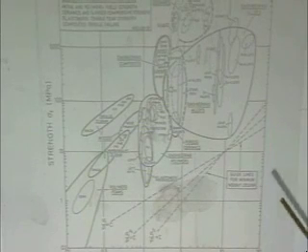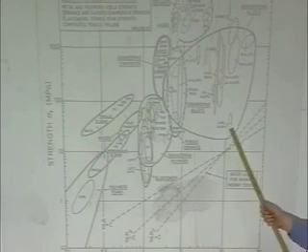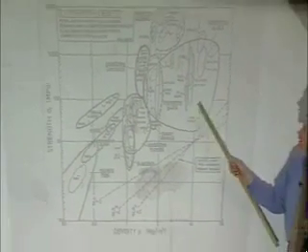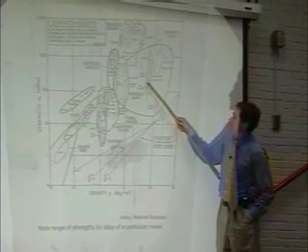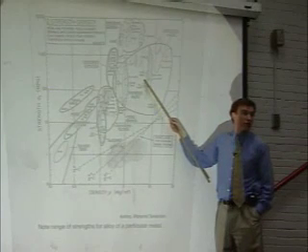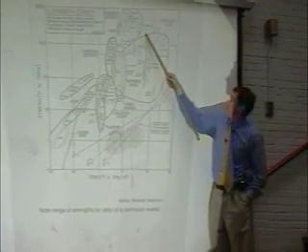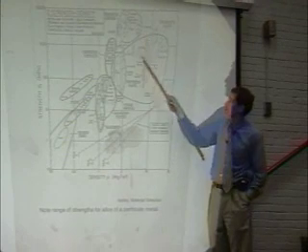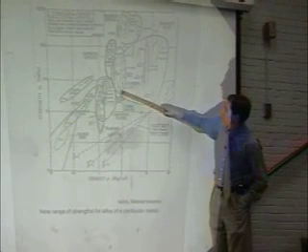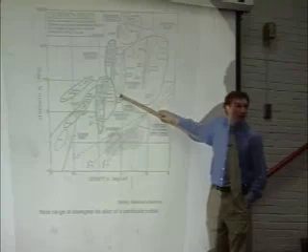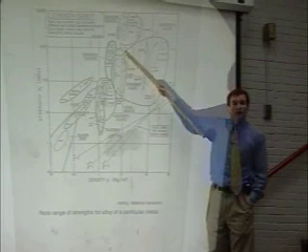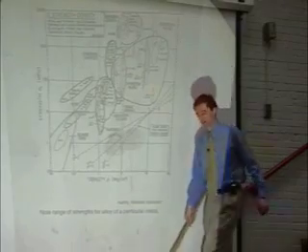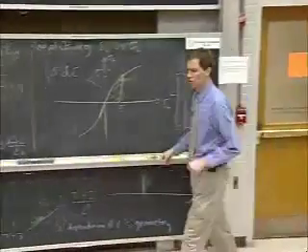And that's what we're going to move on to next time, looking at what the different strengthening mechanisms are that get us from a steel that has a strength of maybe just over 100 megapascals, a mild structural steel, up to a high tensile steel, which might be 2 gigapascals, or perhaps of more importance to us, how we get aluminum from 50 or 60 megapascals up to nearly 700 megapascal strength in the high-strength alloys commonly used in airframes. So that's what we're going to move on to next time, as well as just finishing off a few thoughts on this.